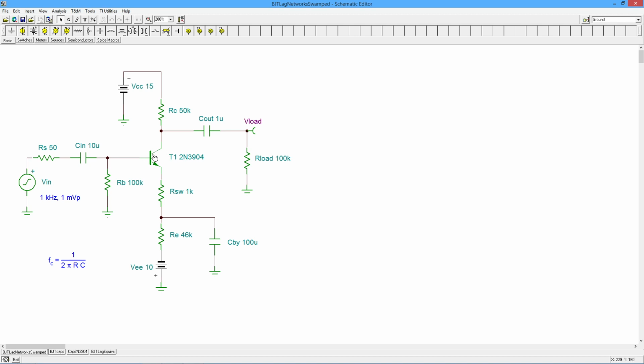All right, I don't see any little capacitors out here that are affecting the high frequency response. Well, you won't, usually. These are small parasitic capacitances associated with the active device. So if I look at, for example, the base to collector on my transistor here, you could think of that reverse bias junction, the depletion region, as kind of like the dielectric of a capacitor. And the base and the collector themselves are like the plates of a capacitor. So that'll produce a small capacitance here. Similar sort of situation on the other sets of terminals. Well, how small? Well, probably picofarads.